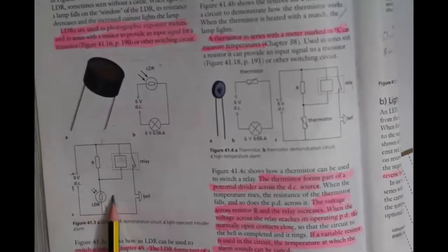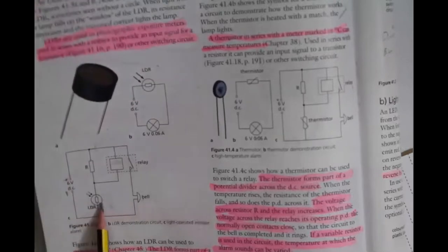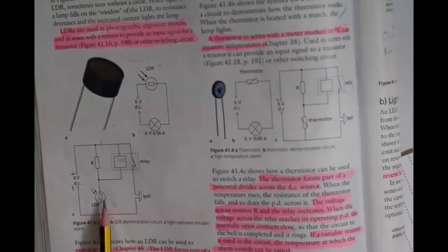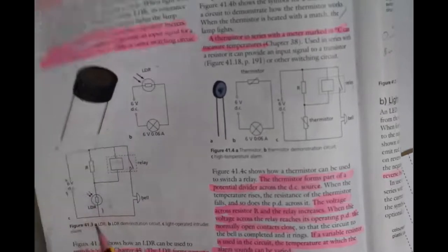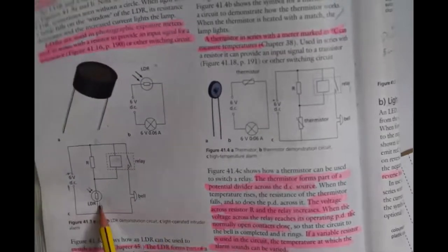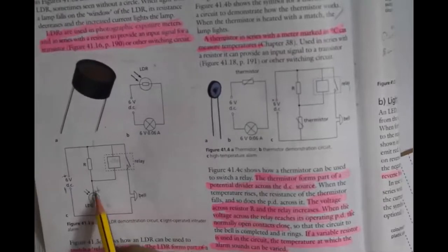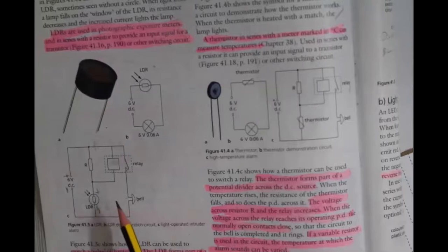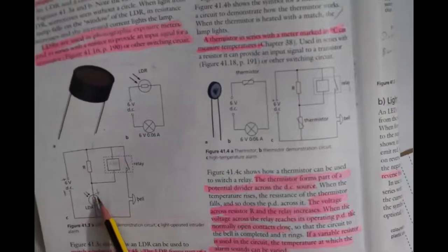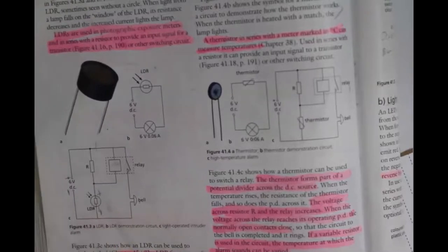So let's suppose we have lots of light. Light intensity is increasing and the resistance of the LDR is decreasing. So there is less resistance in the LDR. That means there is less potential difference across the LDR. We're not talking about any other element of this circuit, just the LDR. So there is less difference in charge across this LDR, because most of the current is flowing. Think of it as a pipe. Because the pipe is wider, we don't have much of a crowd on each side of the resistor, or the gate in the pipe example.